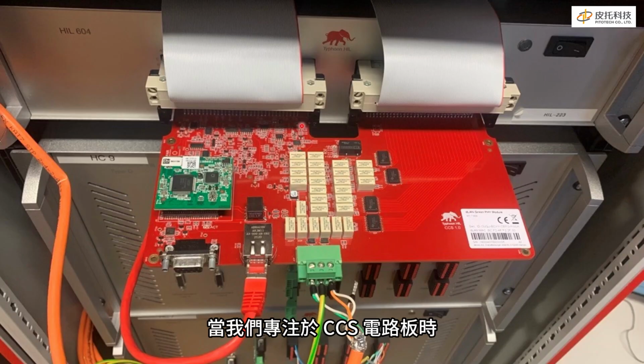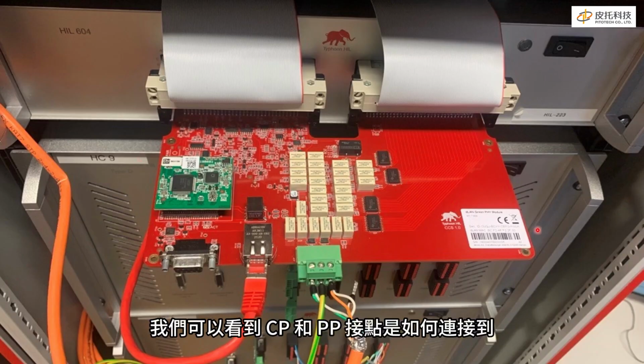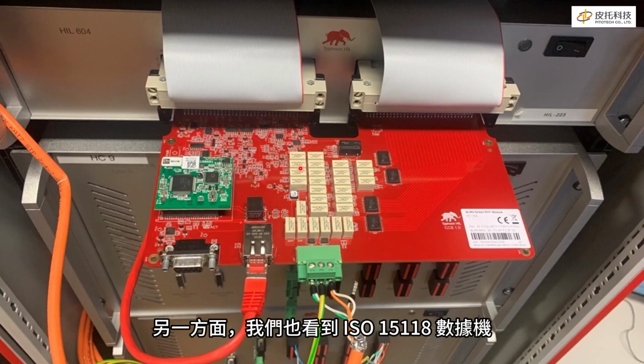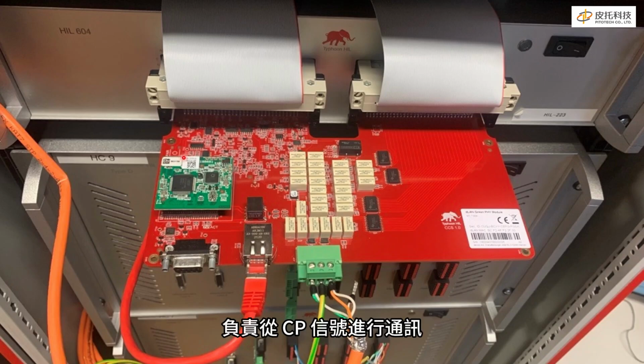When we focus on the CCS board, we can see how the CP and PP contacts are linked to the analog inputs of the Typhoon HIL computer, and we can see various digital contacts which control the CP signal. On the other hand, we also see the ISO 15118 modem, which makes the communication from the CP signal to the HIL interface of the computer.